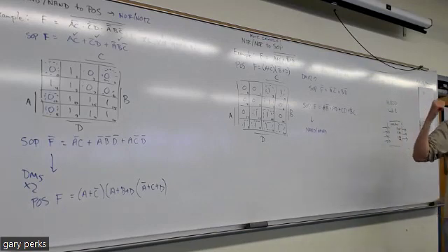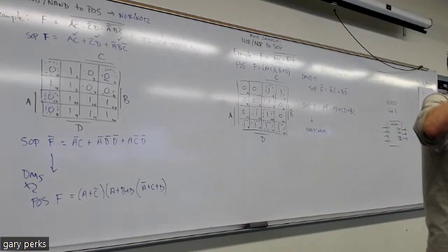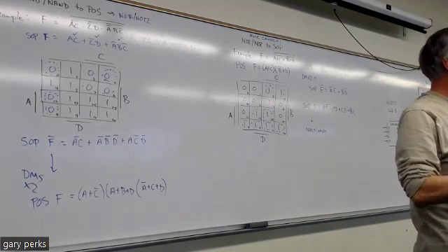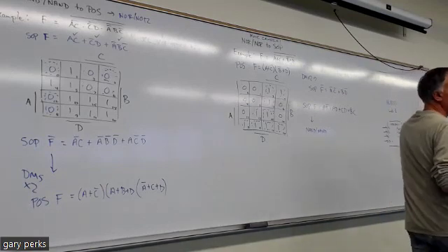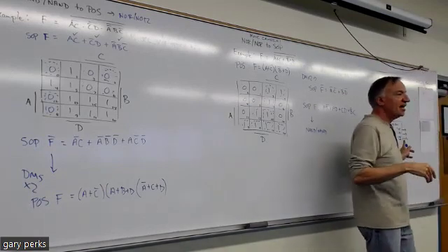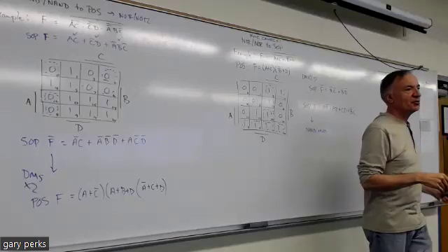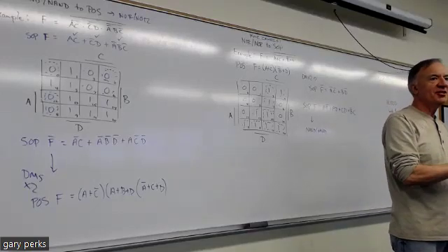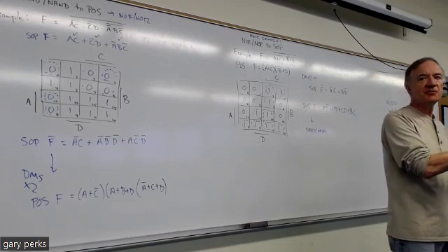When you simulate this design, those 3 outputs should be 1 at the same time. They should be 0 at the same time, right? They should all be in sync. When you test it on your Basys board, you're going to have 3 LEDs, an LED for each output. Those LEDs should all be in step. They should all be on, and follow the same truth table, okay?